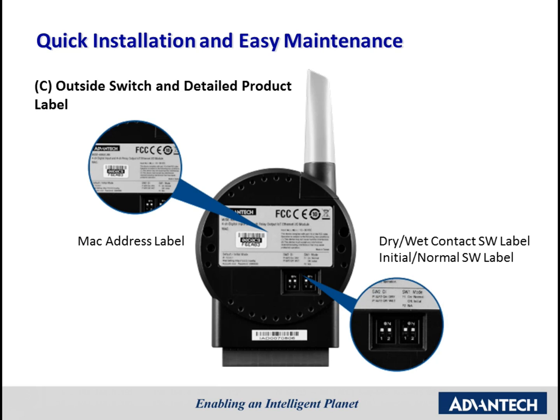WISE adjusts the DI sensor type, dry contact and wet contact, by the switch at the backside. Besides, WISE adjusts its own status, initial and normal status, by the switch too. We put those switches at the backside of the WISE so you can adjust it very easily. Also, there are the detailed label of the switch and MAC addresses on the backside label.